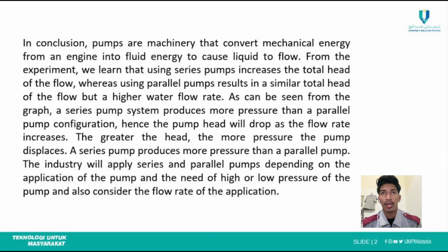In conclusion, pumps are machinery that convert mechanical energy from an engine into fluid energy to cause liquid to flow. From the experiment, we learned that using series pumps increases the total head of the flow, whereas using parallel pumps results in a similar total head of the flow but a higher water flow rate.